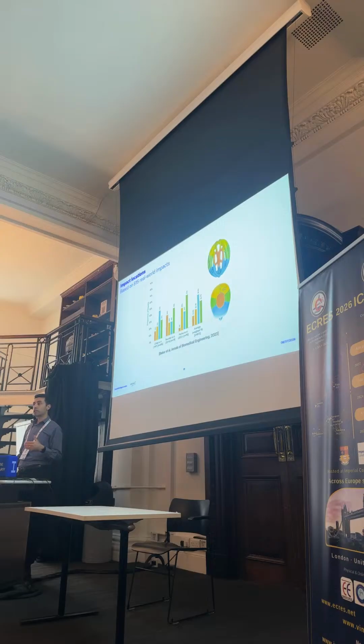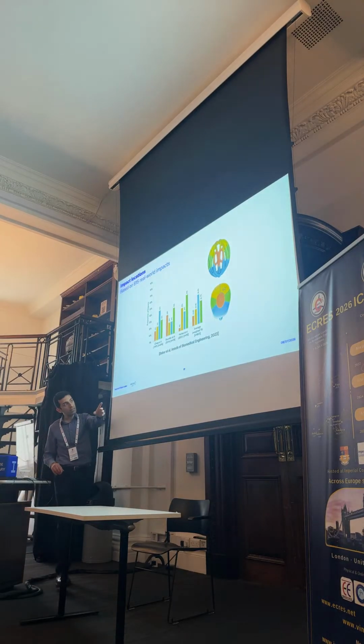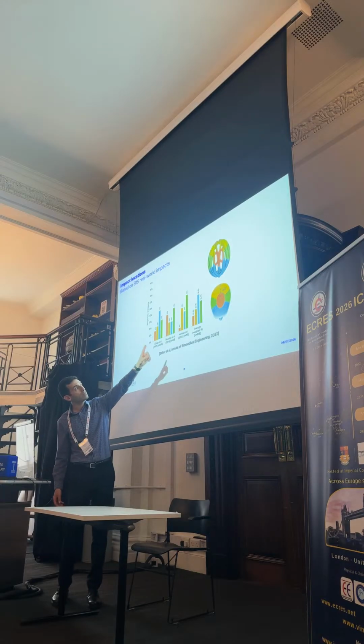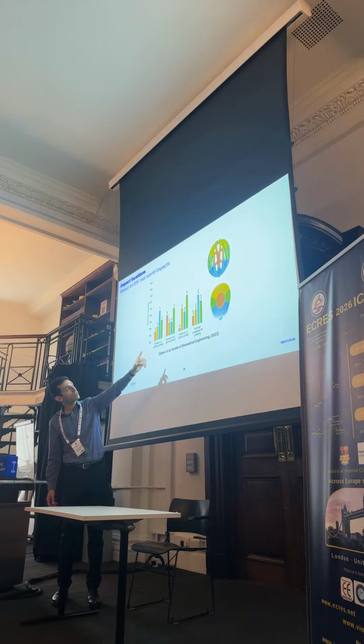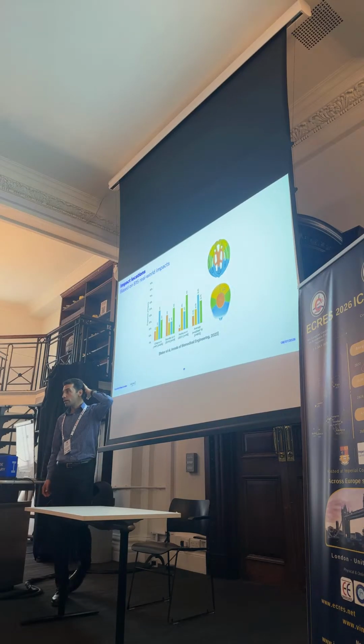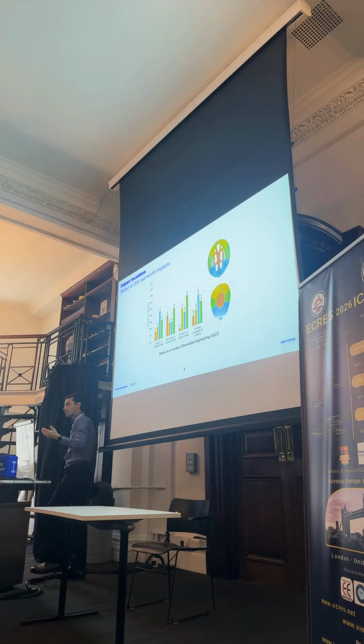What else we did? We didn't want to continue what standards are doing. We looked into actual accidents, and we had around 815 data points from literature, and from that we found which locations on the head are impacted most, and even we could have a weighting for different locations. So you can see here, for instance, if you look at the average, the last columns, you can see the front is impacted most, and then we have crown impacted least, and then we have sides, and then we have the rear. So that weighting you will see later is being used.